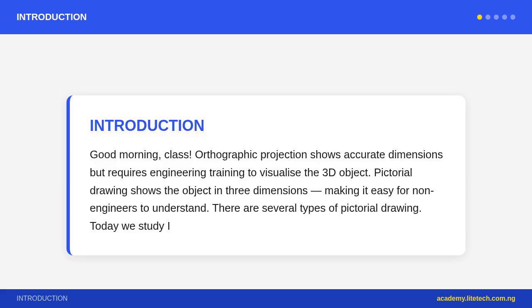3. Lines not parallel to any isometric axis are called non-isometric lines. They must be located by plotting their endpoints using isometric coordinates, not measured directly. 4. There is no perspective, no vanishing point, parallel edges remain parallel on the drawing.